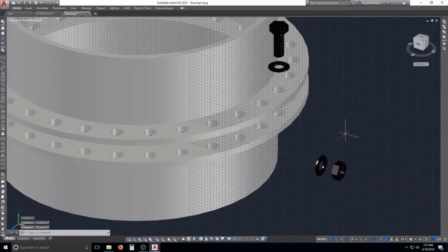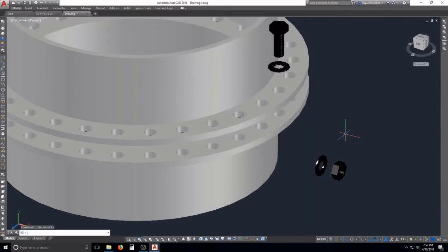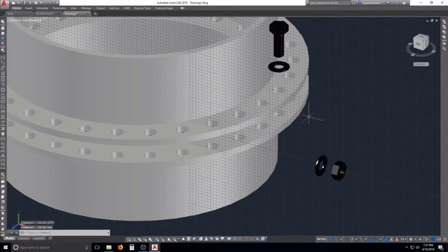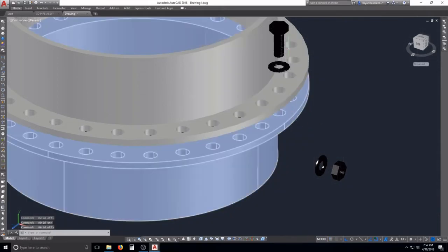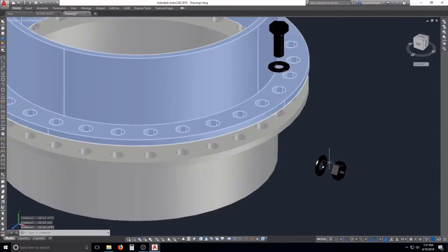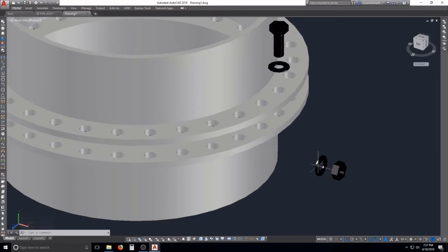Now, polyline is a little bit funny. I know this is probably bothering a lot of you guys, and I don't know why I didn't notice it until now. F7 turns that grid off. I don't know why I didn't have that turned off earlier. So if you want to draw your path, here, what we're about to do is draw your path here, guys. You can do any shape. You can do really a spline or whatever, but start out with just a regular line.